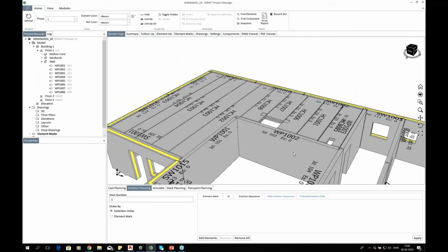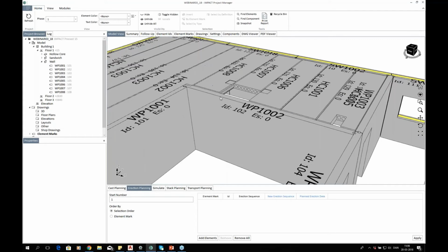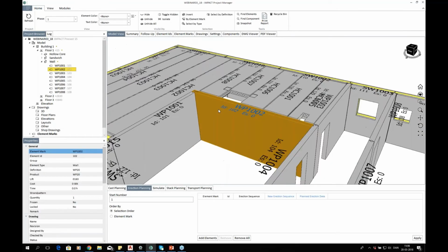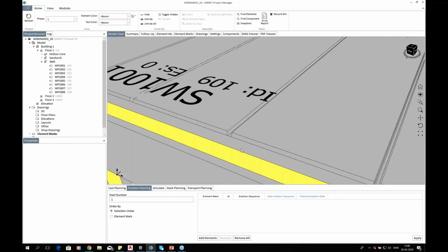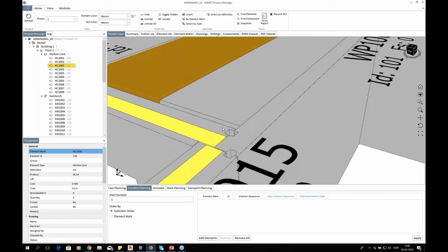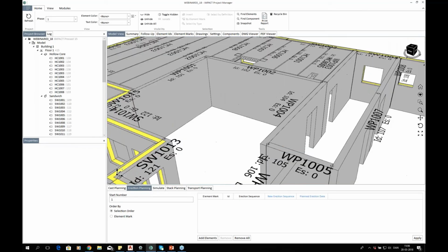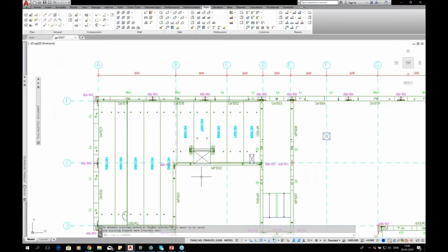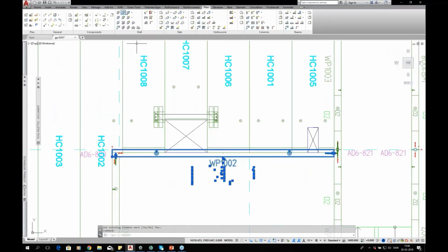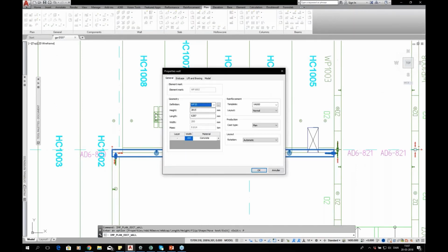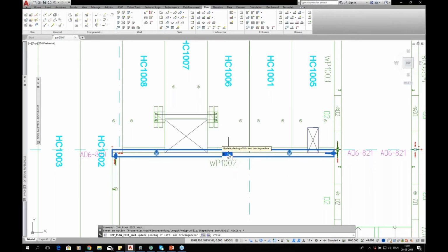So one thing that we can see also now is that this wall is a little bit too high here. And for this wall over here, they're actually not lying on the wall. So we'll just change that. Let's go in here, choose this wall here, and change the height to 26 instead of 28.15, pressing OK.